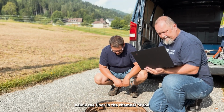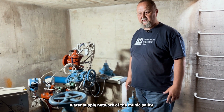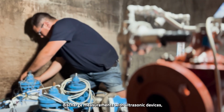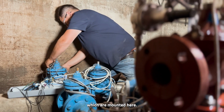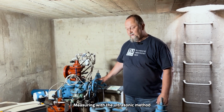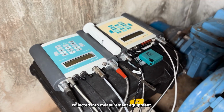We are here below the floor in a chamber of the water supply network of the municipality. What we do here on measurements is discharge measurements with ultrasonic devices, which are mounted here. Measuring with ultrasonic method the discharge through the piping collected in the measurement equipment.